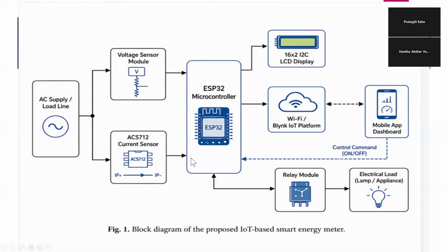During calibration, there is no load current. So the ESP32 can detect the zero current value of the ACS712 sensor. This helps to improve current measurement accuracy. After calibration, the relay turns on and the DC load starts working.